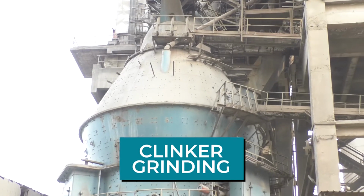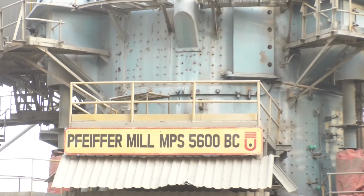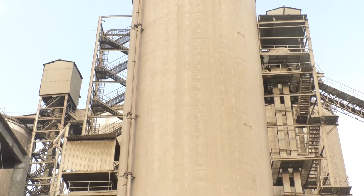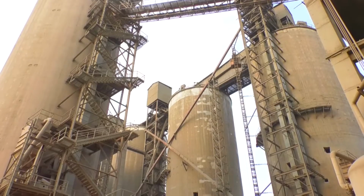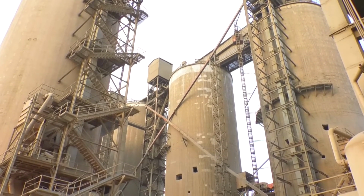Clinker grinding. To achieve a narrow particle size distribution, the clinker is mixed with gypsum and ground with the high efficiency separator circuit of the vertical roller mill. The ground cement is stored in cement silos by a closed air slide conveying system.